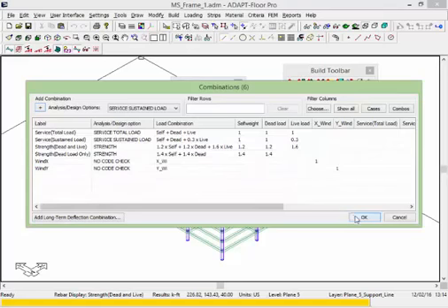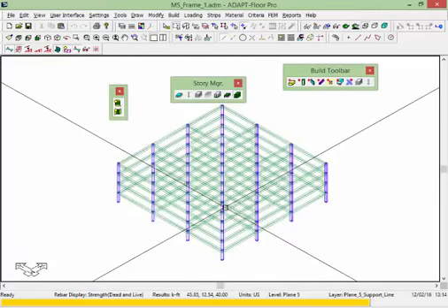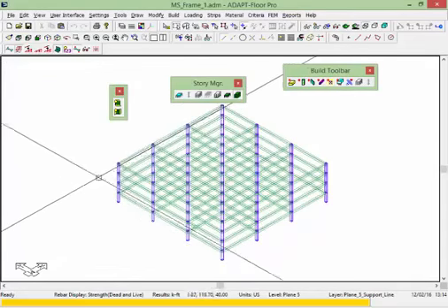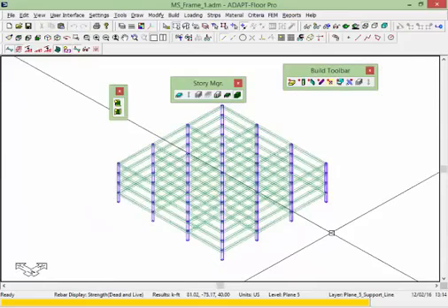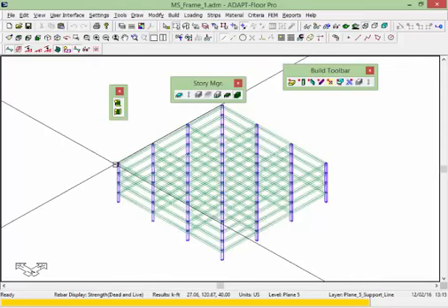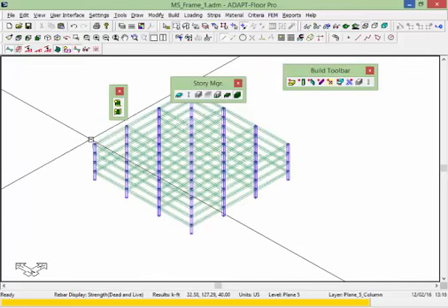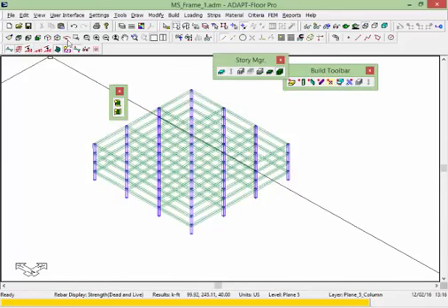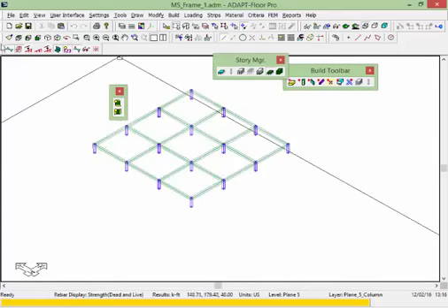And now we want to add loads to the frame in order to mimic those wind forces in the X and wind forces in the Y. So I'm just going to add a lateral load to each of the nodes where the beam connects to the column. So we're going to go to a plan view, and I'll go back up to the roof level, and I'll just add some arbitrary loads to a few of these.